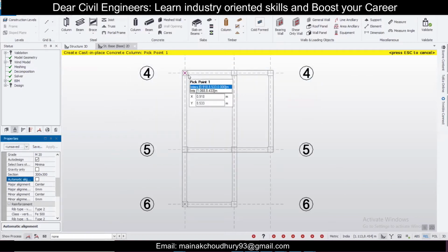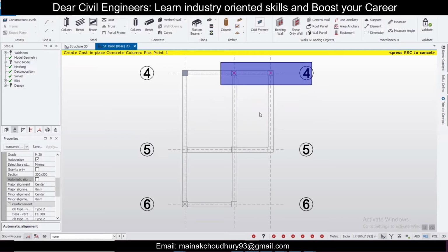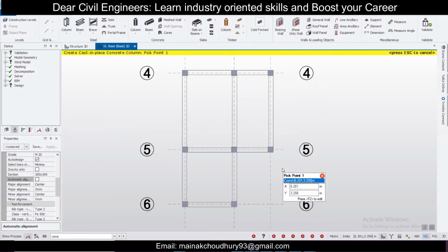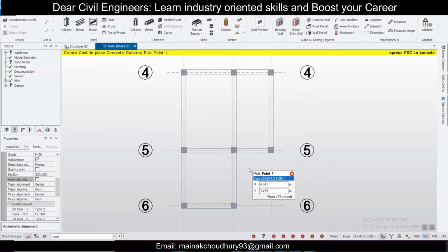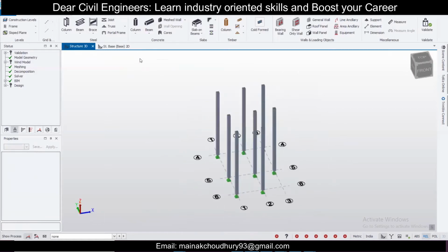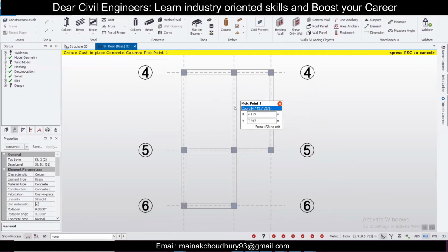After that, we'll place the columns here like this, at all the grid intersections. If there is a point where there is a grid intersection but no column, you can just unselect that. Okay, so the columns have been placed, and you can see the 3D view. These are the columns starting from the foundation level to the top floor level. You can make another level just for these 4 columns because they will go up to a separate level. You can do that now, or later also. Okay, so first of all, let's add the beams here.